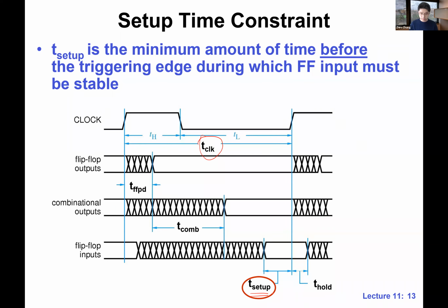So one trick, which I find very useful, and I highly recommend that you use it later on as well when you analyze this kind of diagram, especially for dealing with this time analysis, is to use some reference time. For example, if you look at this clock edge, let's name this time T0. Then we can just say this is time 0. This is my reference time. And we're going to be using this a lot later on.